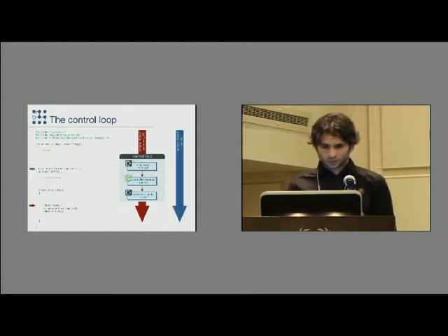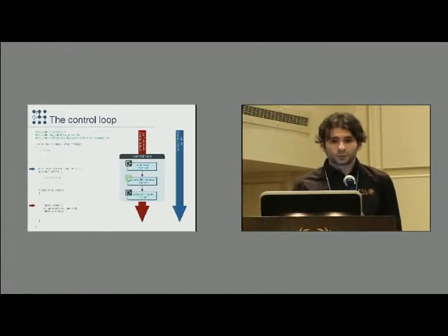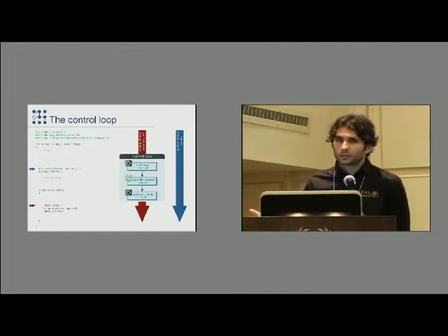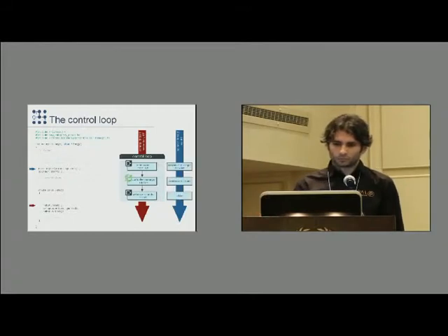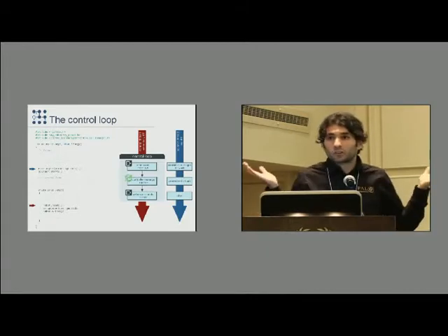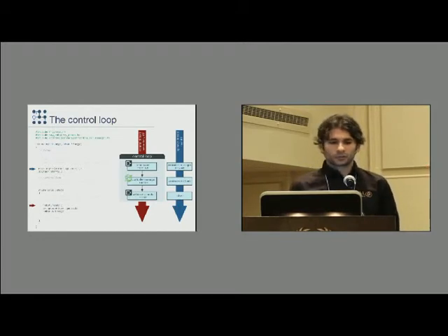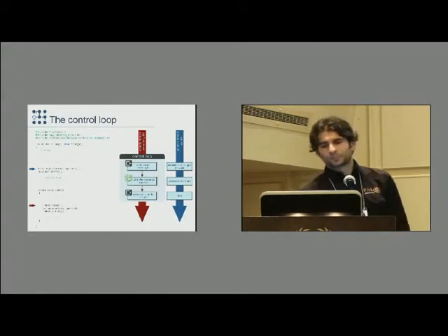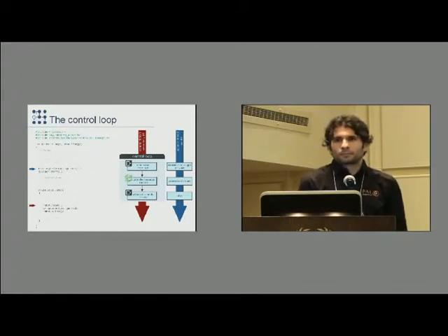And as I was mentioning before, there's another thread called the spinner thread, which is non-real-time and is responsible for servicing ROS callbacks. What kind of callbacks are being serviced here? In the first place, those from the controller manager API, but then there are all the ROS APIs from your controllers, which are custom. And depending on your setup, you might have other things registered there. This is really up to you. But the important thing here is that it's really important to have those things which are non-real-time in a separate thread.